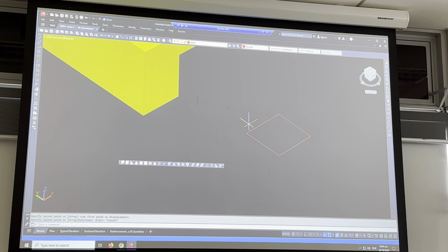Alright, so here's my plate, it's also a P-line. I'm going to click on it, and then I'm going to go to the extrude button, and obviously, is the plate 10 mil? Yep. Thank you. 10, enter. There's my plate, done and dusted.